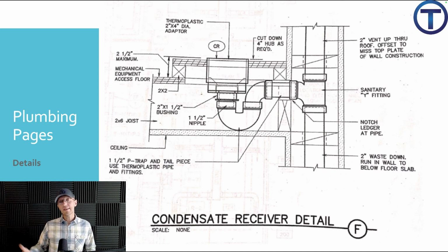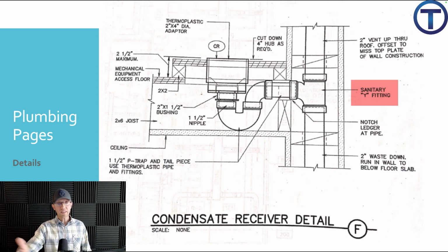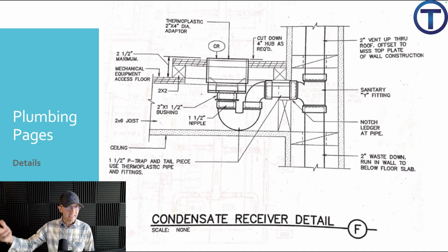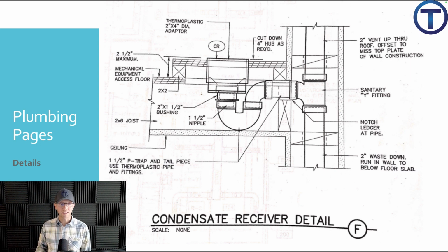Now, once again, let me point out that not all details in these are accurate or correct. Look at this sanitary Y fitting. It's saying sanitary Y fitting is what they want. But according to code, that'd be a Santee, right? You don't put a Y in that situation. It should be a Santee to be properly vented. So occasionally we find things on plans where it's not quite right. And once again, it's okay to ask questions. You can say, this doesn't look right. Hey, I'd like to request some more information. Should it be like this or that? Ultimately, we do whatever the engineer says.